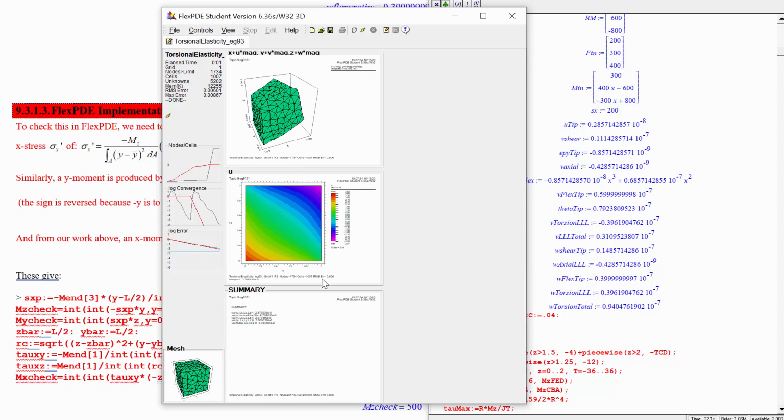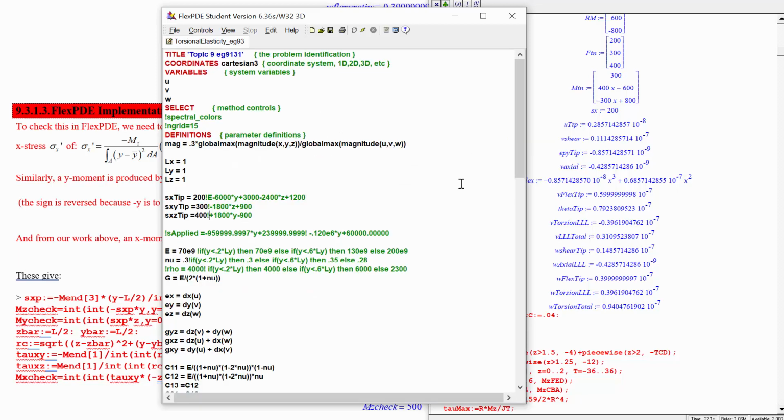So there's some bending produced by the net shear forces on these surfaces, and that is leading to a displacement in the x direction, modifying what we calculated before for the x displacement. So the analysis worked pretty well, except for the second order effects that we ignored when we came up with a lot of this analysis stuff. The fact that bending can lead to some longitudinal displacement as well as transverse displacement.